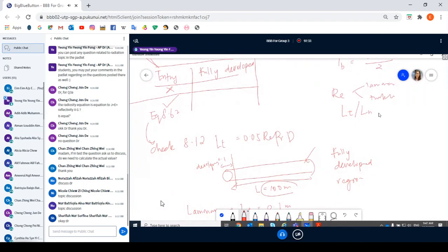After that, you will proceed to the Nusselt correlation. You go back to here and see which case is applicable. This is for fully developed: hD over k for QS constant is 4.36, and for TS constant is 3.66. This is for the fully developed region.